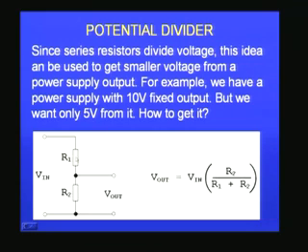And therefore, if I use very large resistors here, I will not be able to get enough current for applying to the different circuits that I have at the output, and therefore one has to choose reasonably small values of resistors for R1 and R2, especially when you want a potential divider. But how small? Can I put 10 ohms and 10 ohms and divide the voltage? Again it will divide equally, and because it is 10 ohms I can get very large current, therefore there is no problem. Yes, you can certainly get very large current using a 10 ohm, 10 ohm combination, but you should always remember